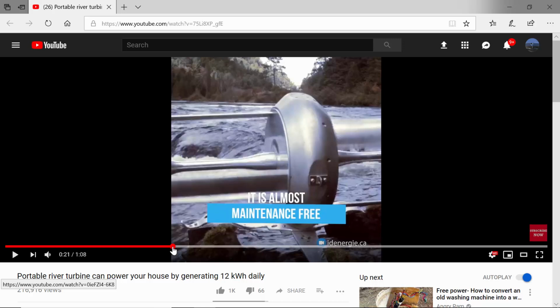where the turbine head is the elevation difference between the two minus any energy losses, like through the pipe or any local losses. So H sub T was largely driven by the elevations. So it's Z1 minus Z2 minus the head losses. So that's how much head there is. And so it was using potential energy to generate electricity. Because remember, energy can be in 3 places. It can be as pressure, as elevation, and as velocity.